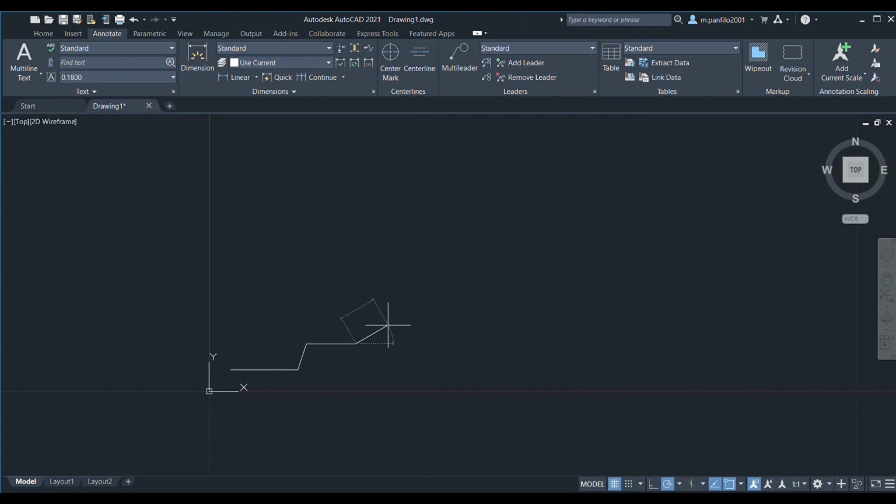All we need to do is get 150. So in order for us to get 150, just first type the length 1.4, then tab, and then type 30 degrees, because 180 minus 30 is 150, and enter.